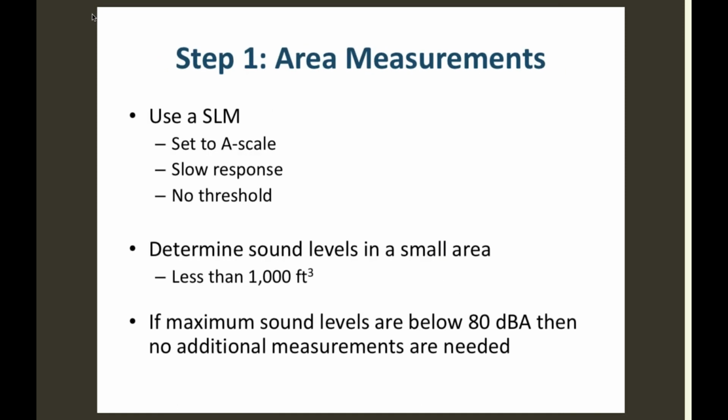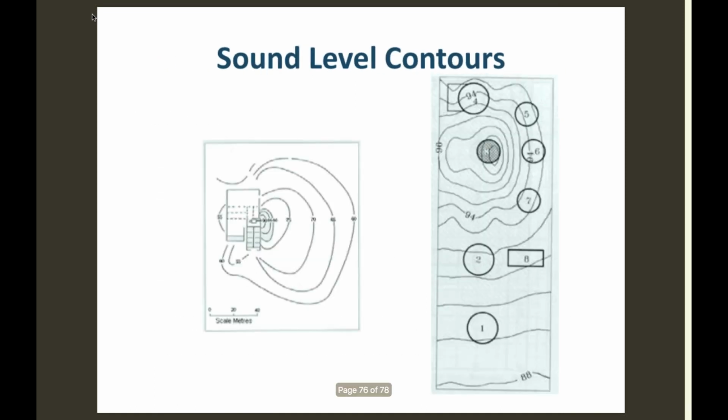Okay, so let me see what we can close out with. Here's a sound contour. We're talking about mapping out sound. With a sound level meter, they've gone around and measured where is 94 decibels. So I read 94 in all these spots along this line. You can predict that as you walk through here, this is, I'm making up numbers, 90 decibels, and as you cross this line, it's 94 decibels, 96 decibels, 100 decibels, and so on. So use that to map out contour lines.